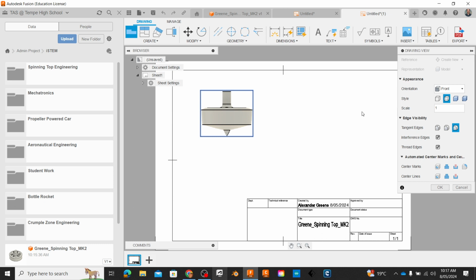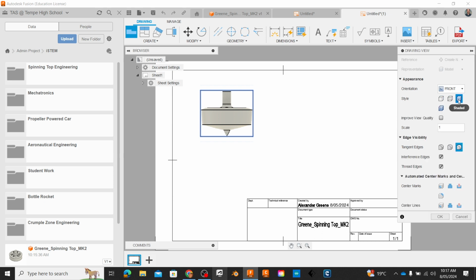You'll have 2 main drawings, and then you'll have an isometric perspective as well. Okay? You can change the perspective here, and you can also change whether it's top or front in this menu here as well. You can also change how the plan is depicted, right? So this will be just vectors and lines that you can see. This will be all vectors and lines you can see. This will be all lines you can see and also shaded. This will be all the lines in the model and also shaded. Okay, so you can check those 4 different types there.